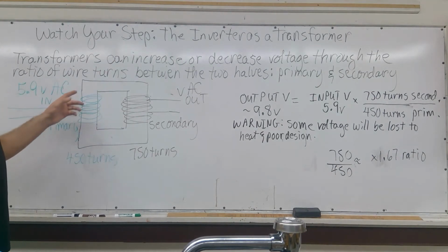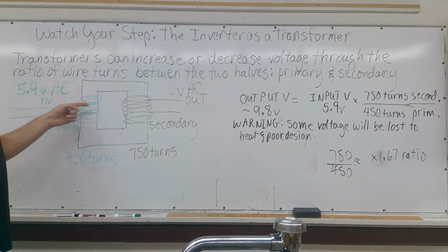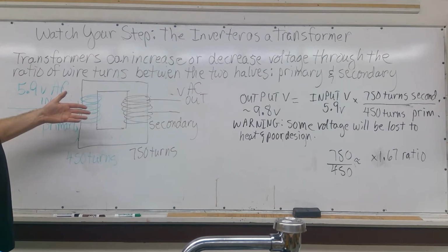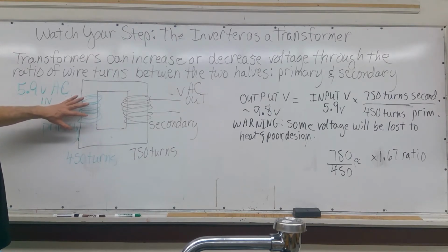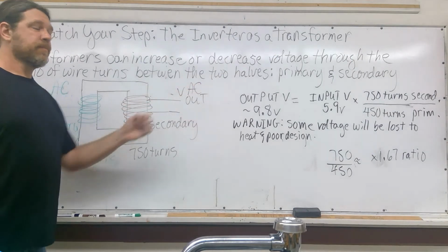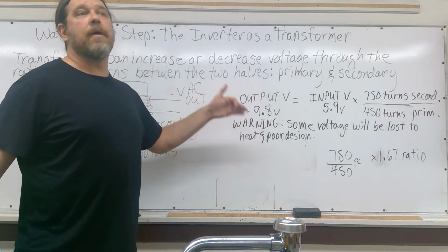Generally, transformers traditionally have been these iron cores that are often rectangular in nature. They're thick, they're 3D. And they have two sets of wires that are coiled. The coiling is what is important because Michael Faraday learned a long time ago that we can build up an alternating current magnetic field from one source of power that excites the electrons in a copper wire and delivers that power over. So what transformers do is take the power voltage of a primary, in the case of the example we're going to use today, 5.9 volts AC, and step it up to a higher voltage of theoretically about 9.8 volts.